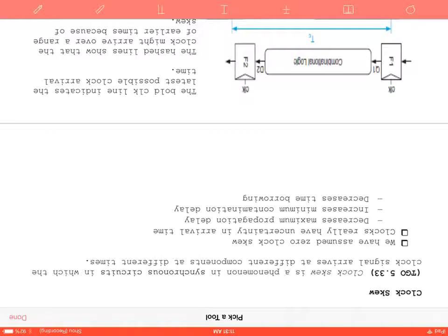But anyway, so clock skew. You're kind of familiar with this concept already in flip-flops. If you're designing a clock and you have a counter and you have different flip-flops, you have a clock that's going to go to each one, right? So you want to make sure that the clock gets to each flip-flop at the appropriate time. If they get there at different times, you could potentially have multiple flip-flops changing simultaneously. One of the ways they get around that is using gray encoding. But this concept of clock skew, when you don't have gray encoding at the CMOS level, becomes problematic.